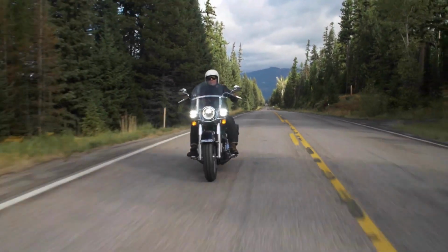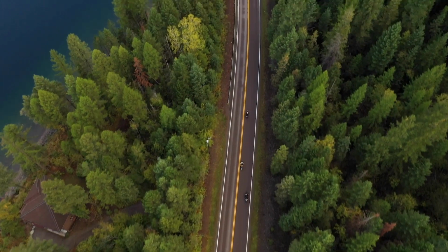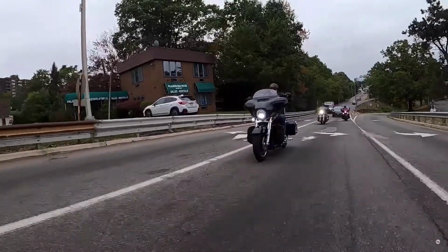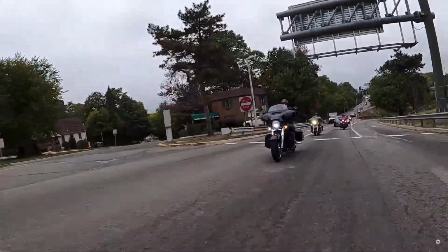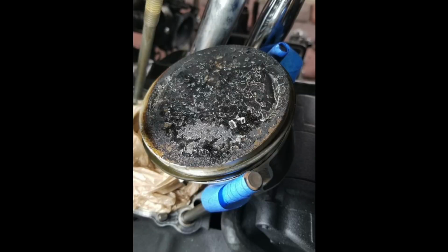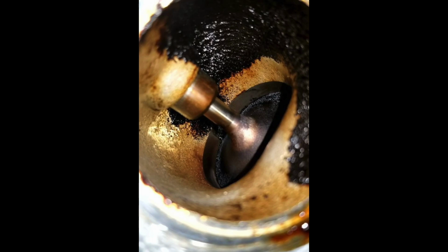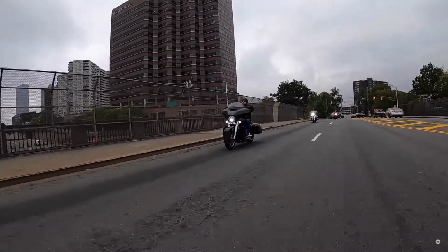A very rich mixture washes off the lubricating oil film from the sides of the engine cylinders and increases mechanical wear. Carbon forms in the combustion chamber and the exhaust tract. Unburned mixture continues combusting in the exhaust manifold, which begins to overheat heavily.